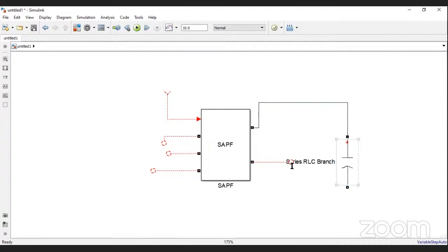So now this DC link capacitor has the capability, if you are maintaining the constant DC voltage at the DC link. So when we apply the fuzzy logic controller here, it will help to minimize the ripples of the DC link capacitor, because we are synchronizing with the grid and load side, right?